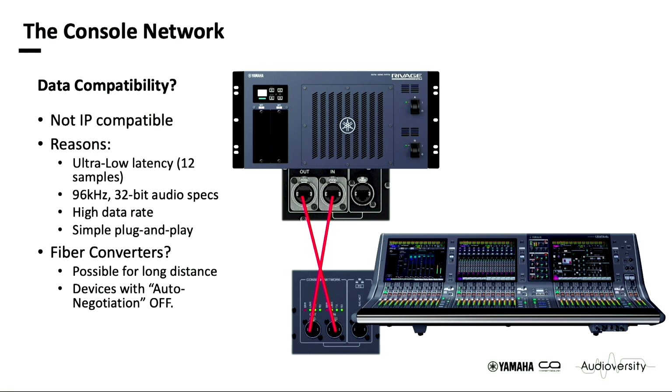Now, some customers have needed more than 100 meters distance between the DSP and the console. Most people keep DSP and console in the same location, so they're generally using less than a 10-meter connection. But some people, for various reasons, want to have a longer distance. So you can use some fiber converters, to go up to 2 kilometers, for example.